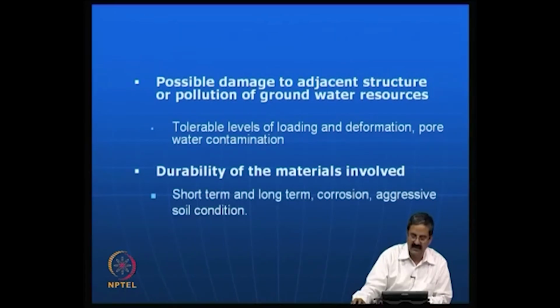So, aggressive soil conditions are another important problem, because finally whatever ground improvement technique you are using, say for example, you are putting some reinforcement, the reinforcement should be working for about 30, 40 years or 50 years. If the reinforcement is dissolved because of aggressive soil conditions or some other problems, or somebody removes it, then it is a serious issue.